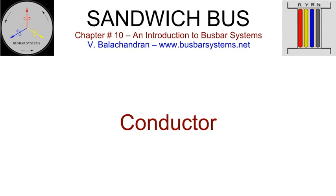When the current rating exceeds that delivered by the maximum bar size, busways are manufactured in 2 or 3 separate stacks as detailed in the configuration. Conductors of each phase are connected in parallel at the ends. With such configurations, it is possible to design a busway suitable for a current rating of 6,300 amperes with copper conductors and 5,000 amperes with aluminium conductors.